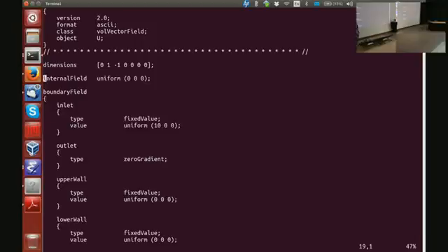Okay. Time to teach you some tricks, right? I want to initialize my internal field to 20 meters per second to help my solver converge properly. And then I want to say that the value at the inlet is the same as the value that I used for initialization. Okay? So what I can say is something like this.